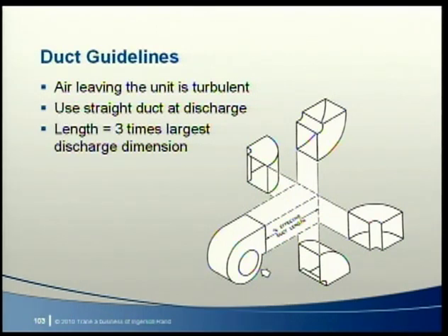This is especially true for duct discharge units where the fan discharges directly into the ductwork. The system effect issues that John mentioned can dramatically degrade the acoustical performance. For these units, both the distance from the fan and the direction of the first turn are important. The ASHRAE Handbook and the ASHRAE Practical Guide to Noise and Vibration Control provide guidance on selecting discharge configurations to minimize sound problems.